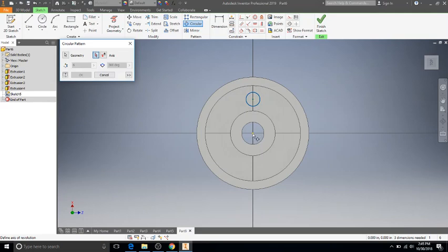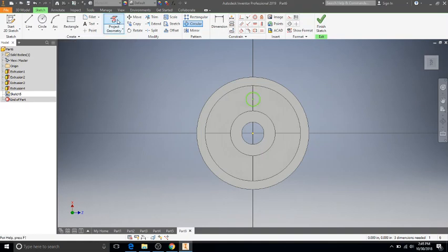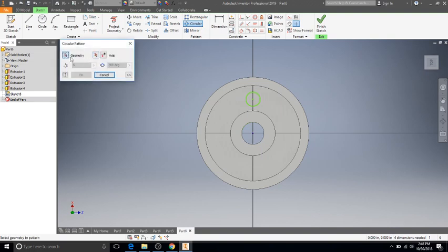I want to spin it around this point, which is currently not in our sketch, so I'm going to project that point onto our sketch if it's allowing me to, which it's not. Alright, let's try that again. Can I snap my circle? There we go. Alright, perfect. Now I got a point to snap to. Let's do our circular pattern. We're selecting the geometry we want to repeat. We want to repeat this circle. The axis of rotation is going to be...